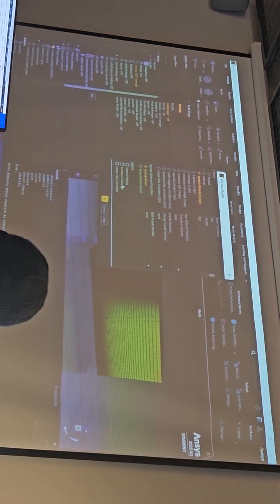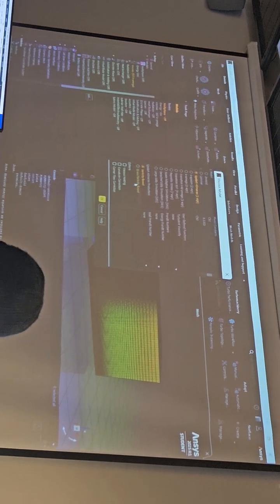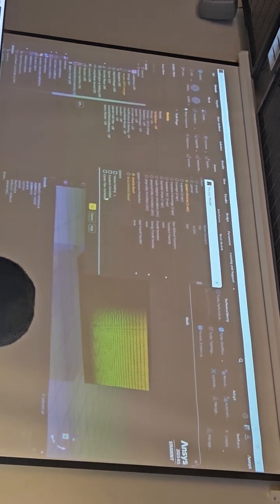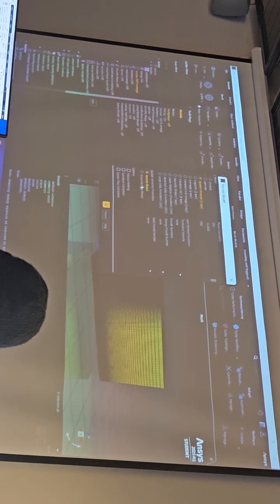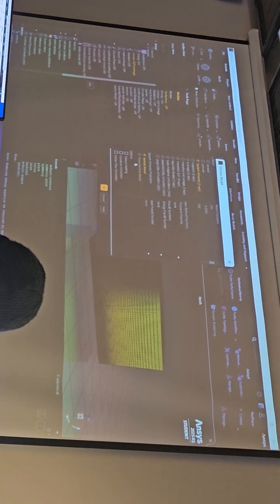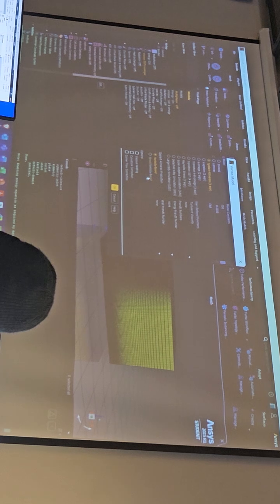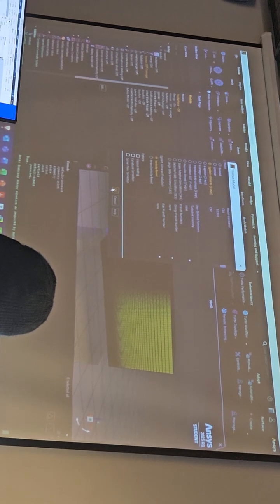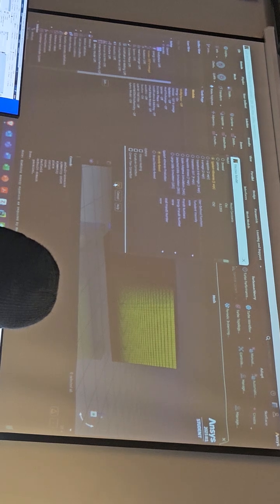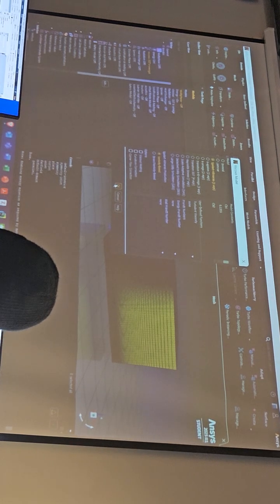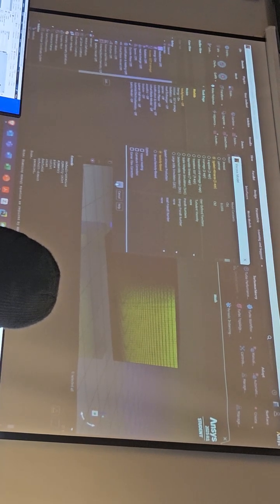We have some options, but we don't need to enable these options for this case. And there is also a production term we can choose if we want vorticity based or strain vorticity based. We are going with the default one, the vorticity based. So if you want to know more about the theory of these models or how they are implemented in Fluent, now select OK here.